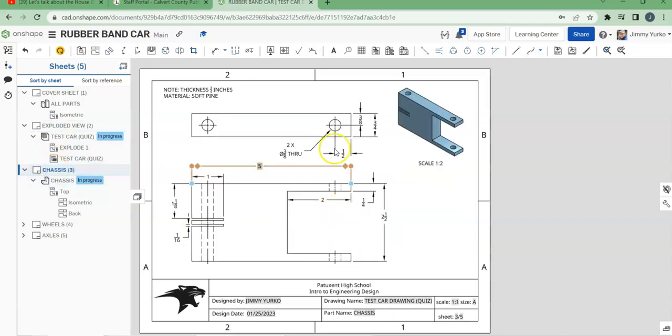We're going to create all the components, and we're going to start with this drawing, which you should have on paper. When you look at your drawing, you'll see that we're going to construct a block that is 5 inches long, 2.5 inches tall, 3/4 of an inch thick. We're going to cut away a section from the middle that's 2 inches deep and is 1/4 inch from each edge. So let's go ahead and do that now.